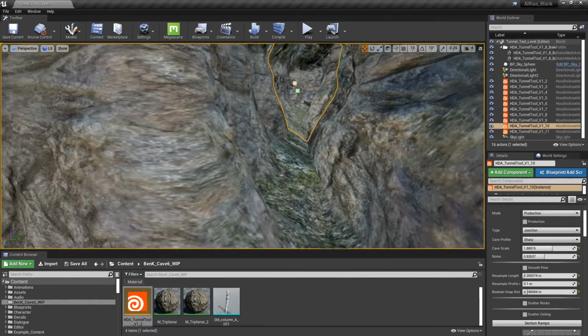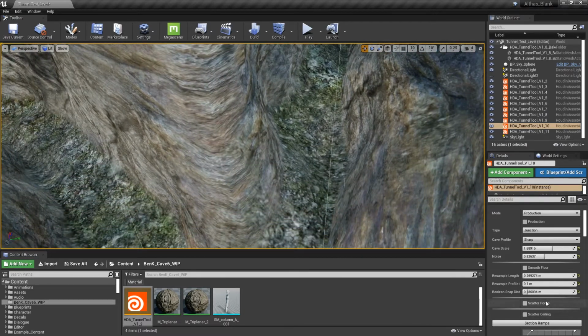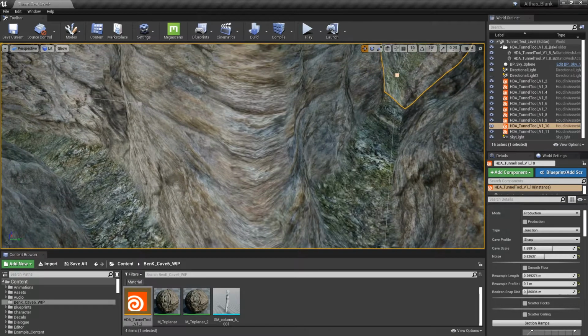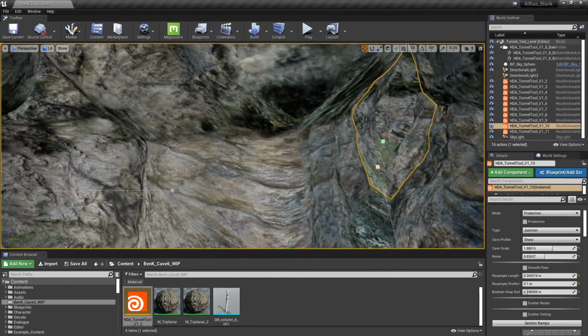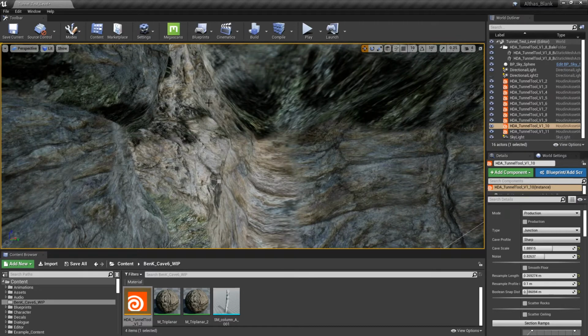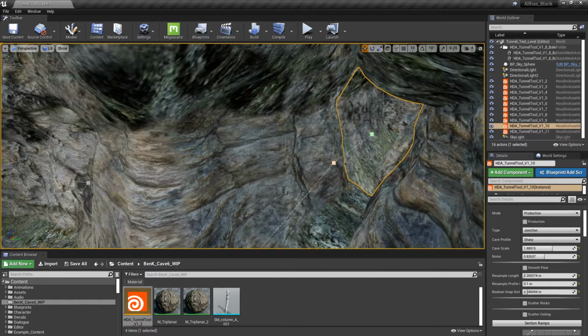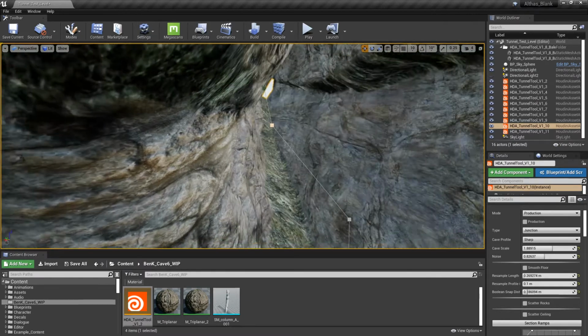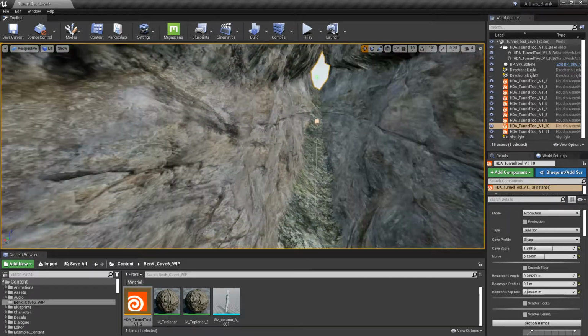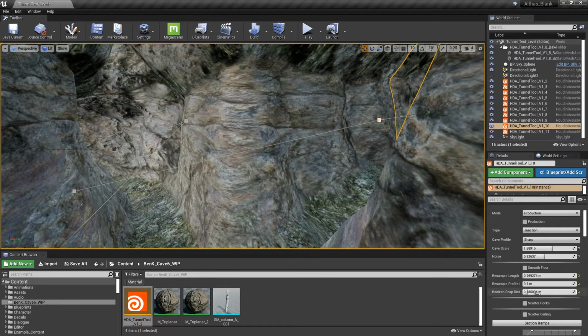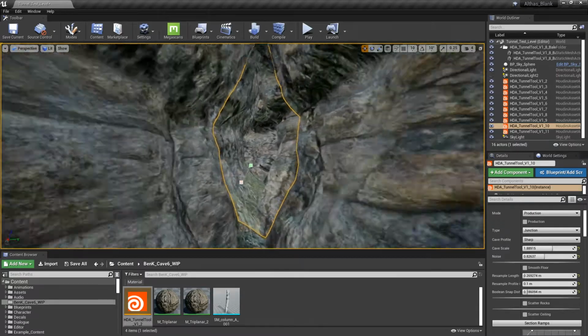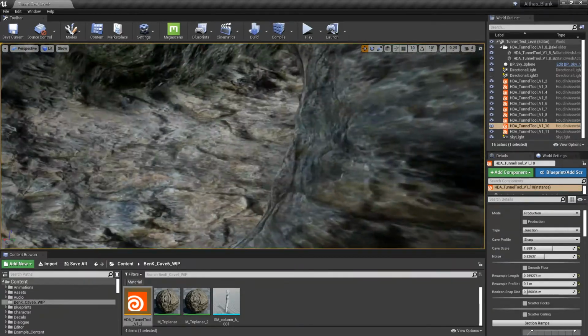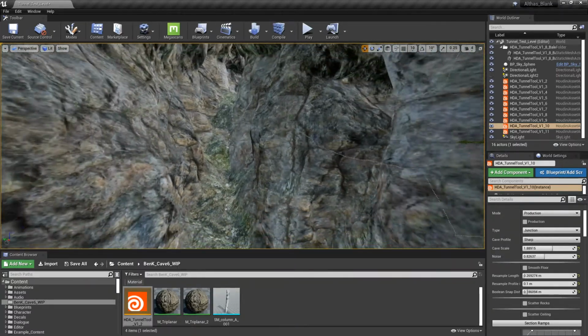One thing to bear in mind, if you increase the Boolean snap distance to higher than the size of the quads, it will start to collapse the entire tunnel down into smaller quads. So it's not a thing that will break it, but just something to be aware of. Use the Boolean tool only when you need to, and use it carefully. Okay, so that's looking quite nice.